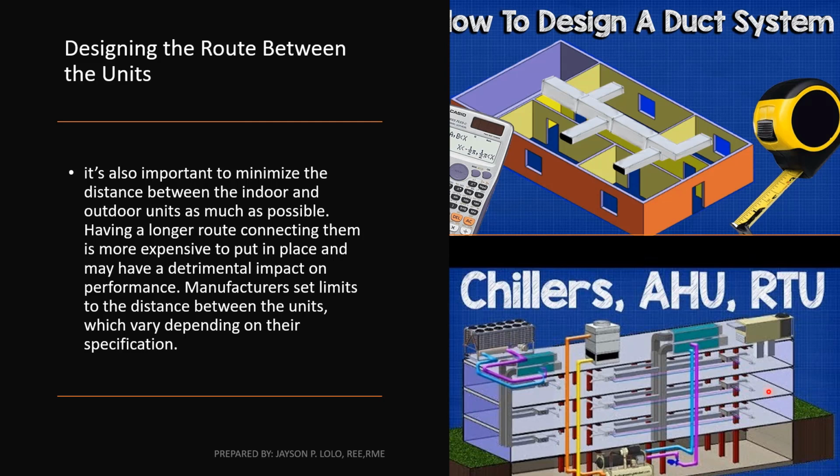For example, if we occupy one room of a multi-story office building and need an outdoor unit on the roof, we need to plan very thoroughly in order to make the installation feasible. If the initial site survey is not done properly, the time and cost of the project could escalate dramatically. So this has negative implications for both the installer and customer.